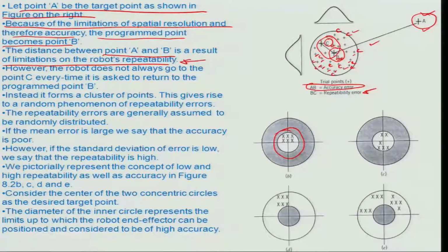If I had a lower repeatability error, obviously these are cases where the repeatability error is lower. In fact, slightly higher, but then again within the same range can also be treated. So, this is essentially the radius within which such C points would be positioned with respect to the actual point B, which is inaccurately being traversed while the programmed point was A, and so on and so forth.